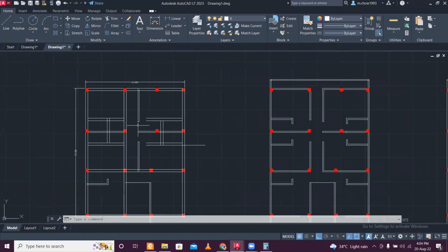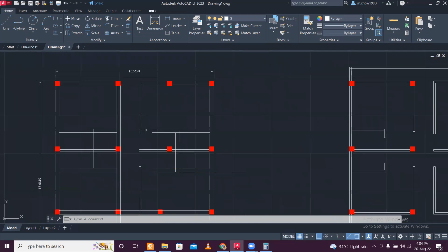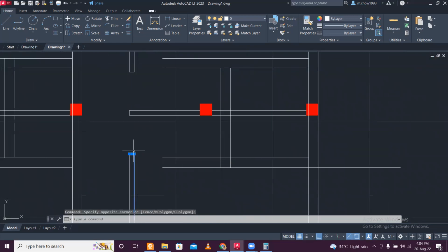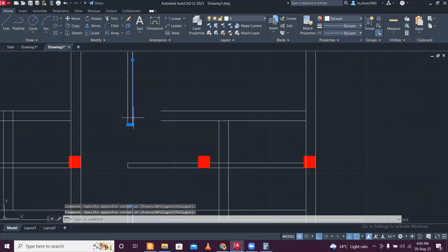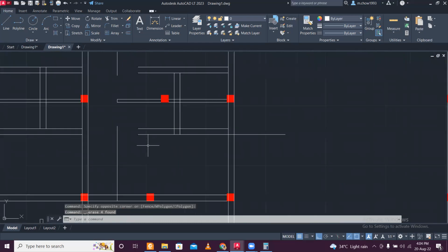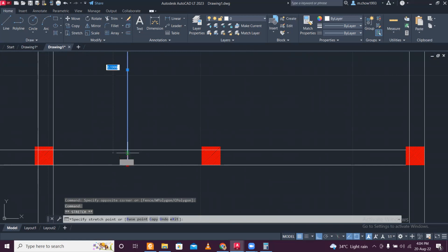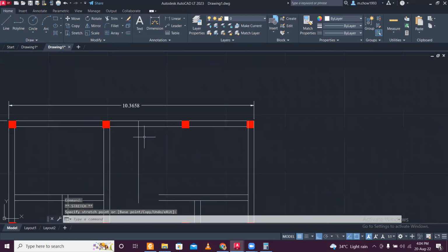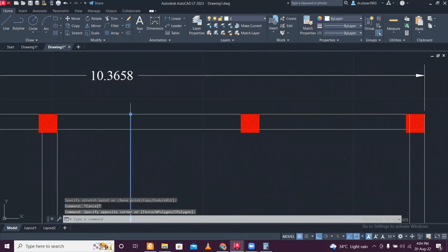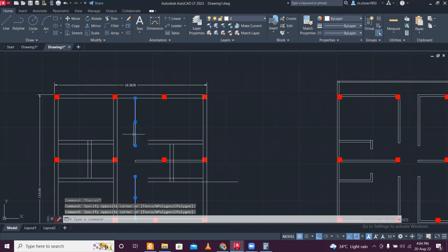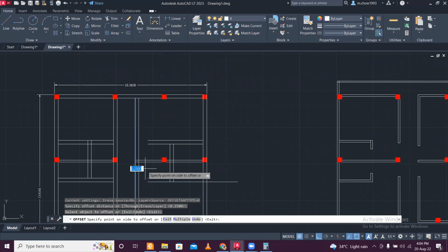Yes, it's done here. Now for this particular wall, we have to give the offset. We'll start from here. Offset will be along the right side of your screen. You should remember that. Let me select this and press J, enter, join, and then O 250 like this.